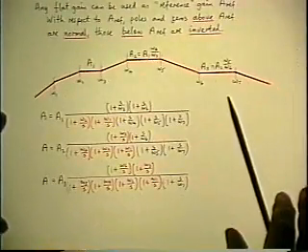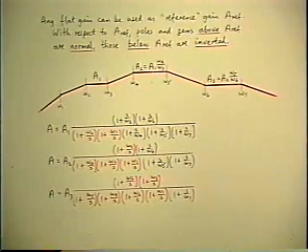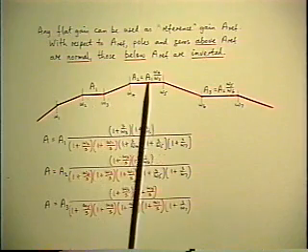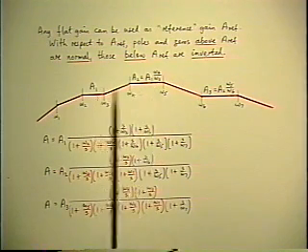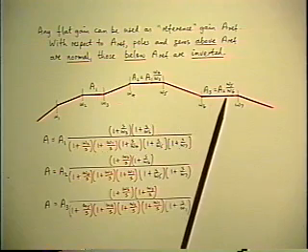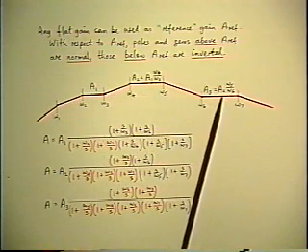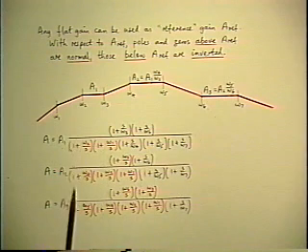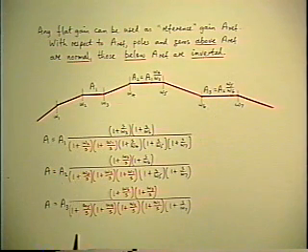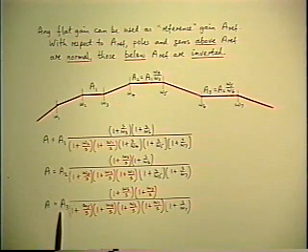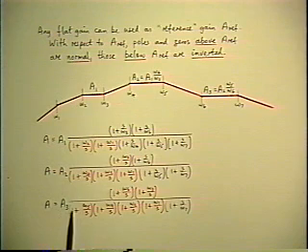And here's a little more complicated case just to illustrate that. There are three flat gains. I've already written on the picture necessary relationships between them, employing the gain bandwidth trade-off ratio. And here are three different versions of how to write the factored pole zero form, choosing each of the flat gains in succession as the reference.